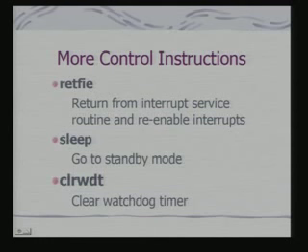What does that mean? It means that when an interrupt occurs and you are servicing it, interrupts can be disabled, so that the current interrupt service routine is not further interrupted. Now, this is also important for PIC. Why? Because of how the nesting of interrupt service routines is to be managed.